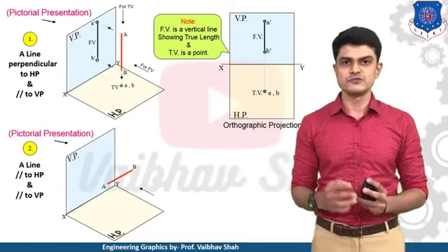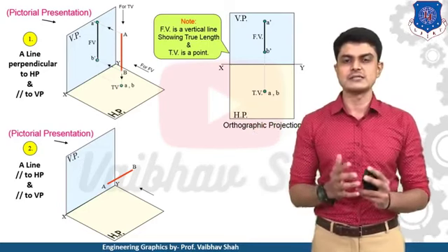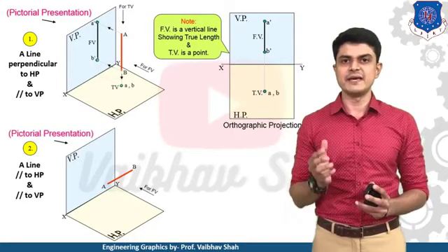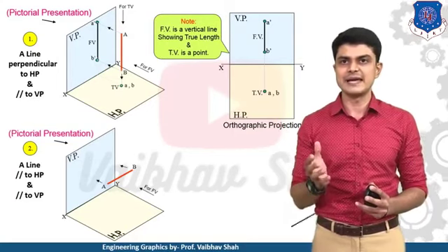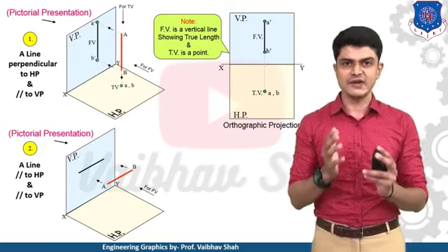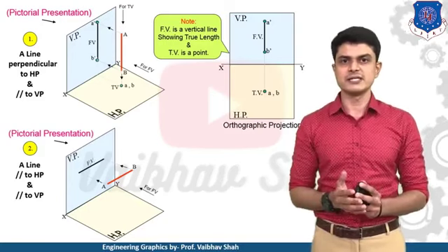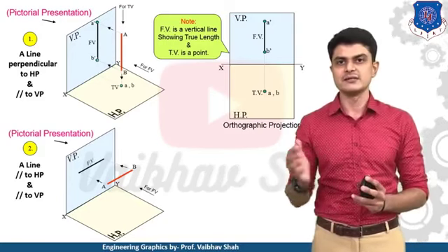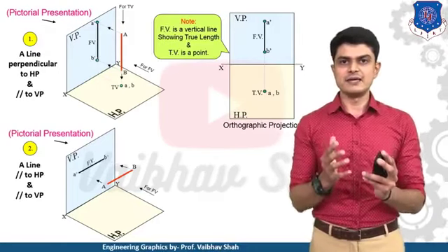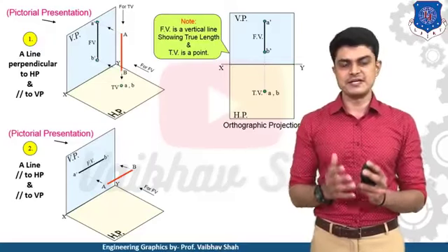So let us take two views. First the front view and second the top view. So when we try to take the front view from this direction, you will be having one line parallel to your given line AB like this. So this is the line having the same length as that of the actual line. So this will be nothing but your front view, and you can say it as A dash B dash, because we are naming the front view as A dash B dash.